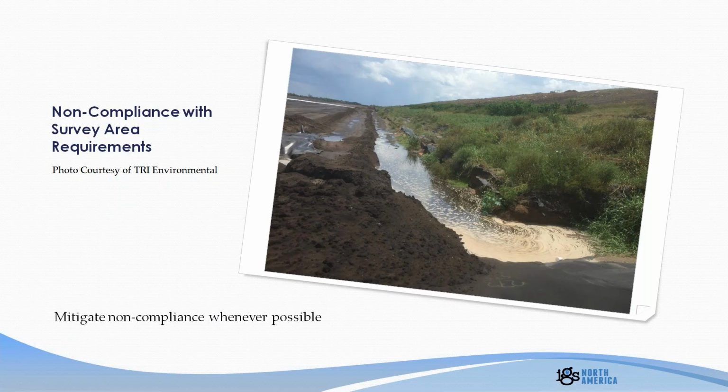This shows an isolation trench. This type of non-compliance is not acceptable. So part of the standard is making observations about all of the compromised isolation issues and mitigating them before the test. You want to make this test maximally sensitive. When you have something like an isolation trench filled with water, you have to pump. You can do a quick functionality test, see if it works, even if it's there. If it truly is impossible to remove this liquid, you might have to do the test anyway, but this becomes part of your testing results because this is a huge factor in how well the test works or whether it's going to work.